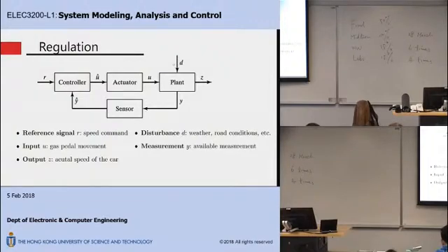The controller takes both the reference signal and the actual measurement, basically the outcome of the plant, and makes some kind of comparison. So these two pieces of information: this R is one piece of information the controller receives, and R in general changes with time. Y, the measured signal, the feedback signal, is the second piece of information, and it puts them in and generates